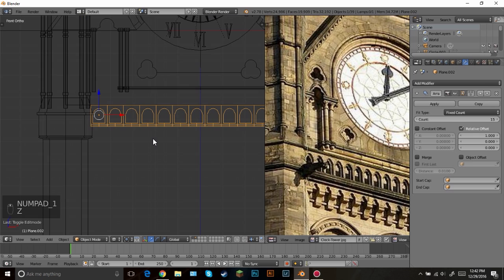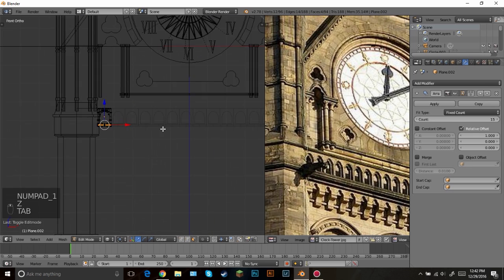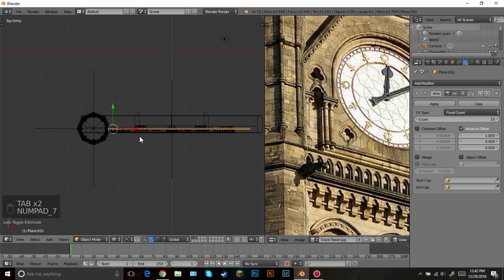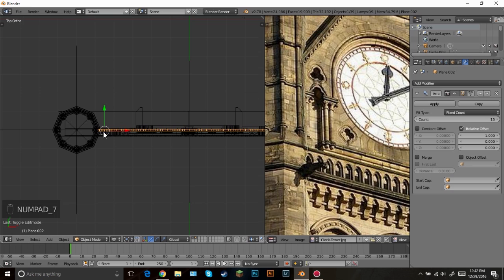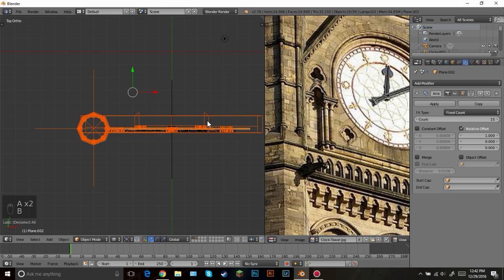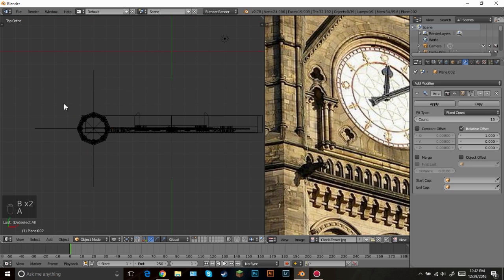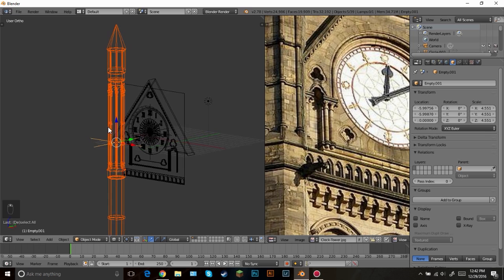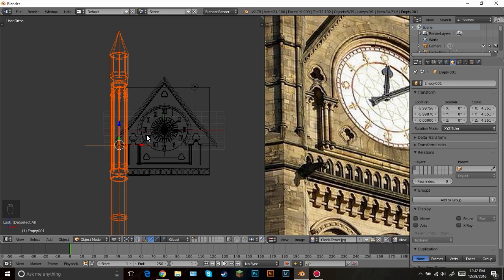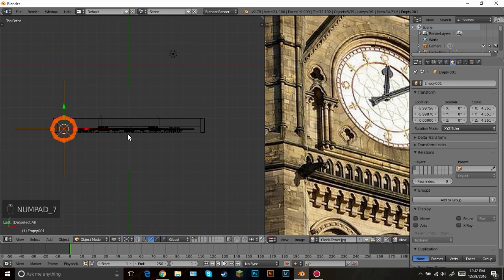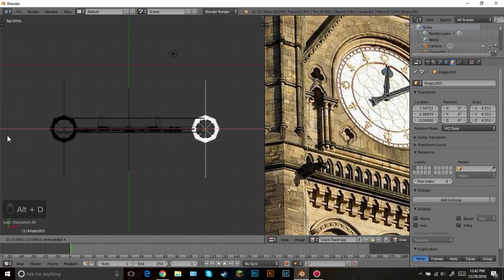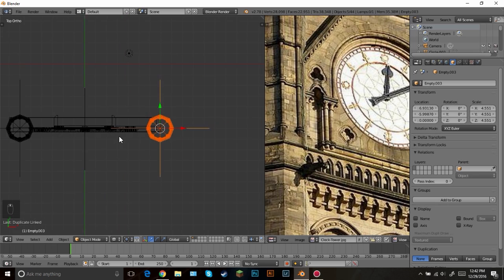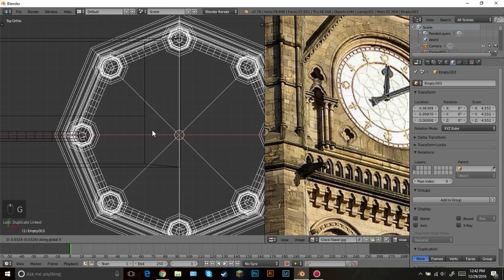Awesome. Then let's duplicate this pillar a couple of times, or just this part, so we can see what it looks like. So go into top view, box select the pillar, and then deselect everything else. Make sure everything is selected in the pillar. It looks good. Then just press Alt D and then move it over here. Make sure it's completely lined up.